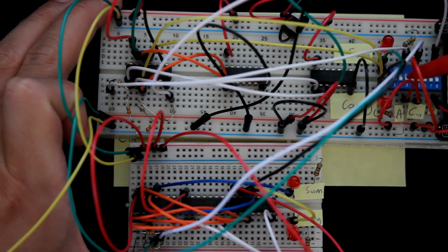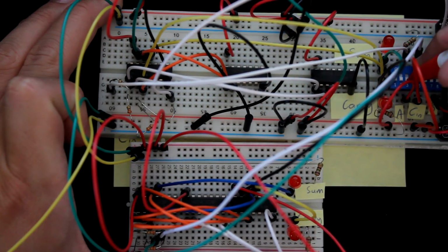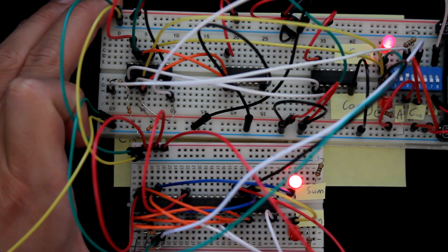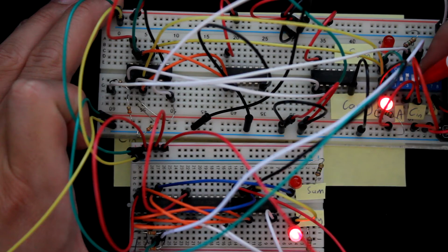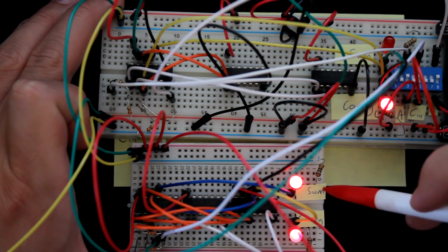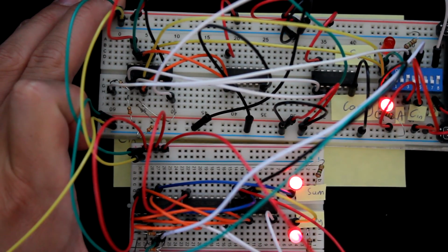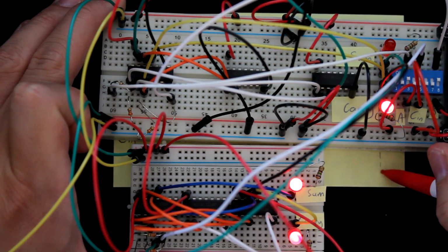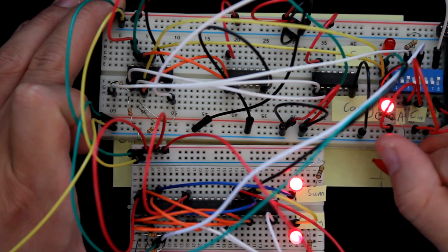This will represent one half adder. This will represent the full adder. So like the single half adder, when I put a single input, the sum is 1. When I put both, the carry is 1 and the sum is 0, just as in the half adder. However, when I turn on the carry in bit, you can see that the sum is 1 as well. So 3 bits of 1 will cause a 1 and a carry.